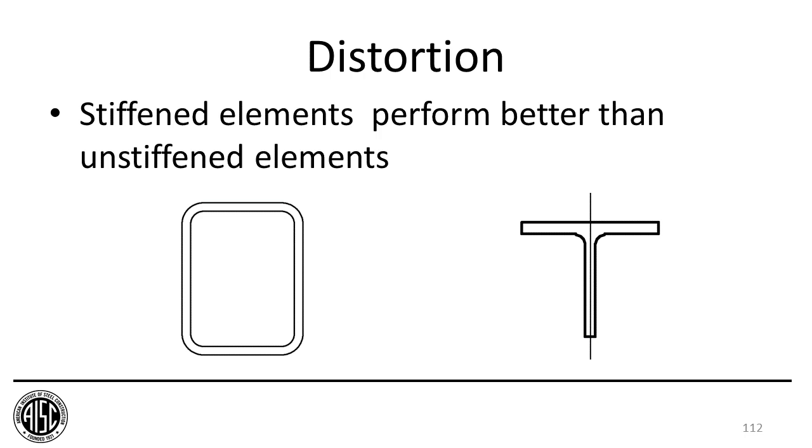But there's a study out there that discusses the loss of camber, for example, due to the vibrations on a truck, and it's been said that the same thing happens to curved members that are curved to a tighter radius than a typical camber.